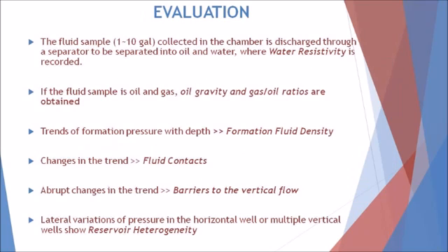The fluid sample collected in the chamber is discharged through a separator to be separated into oil and water, where water resistivity is recorded. If the fluid sample is oil and gas, oil gravity and gas oil ratios are obtained. The changes in the trend represent fluid contact, and average changes represent barrier to the particle flow. Lateral variations of pressure show heterogeneity. That's all from me. Thank you.